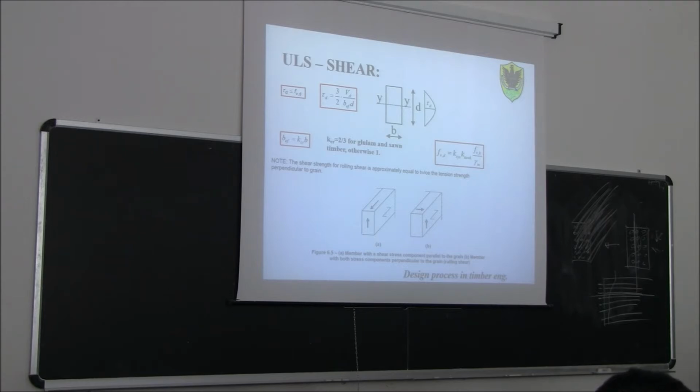So is there no difference between a cut done in the middle and the other? No, there is a difference, in the sense that if you have this kind of shear plane here, for sure you are going to have a break in this way here. You will never have a break in this way here because this will take a higher load. So as you increase the load, first you get the failure here, and only later you would have the failure here. But this is impossible because your beam will already have failed. Okay?